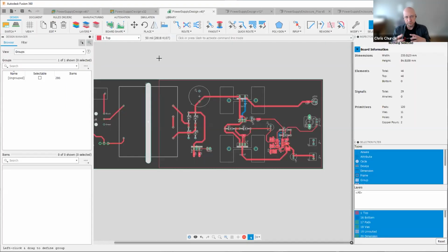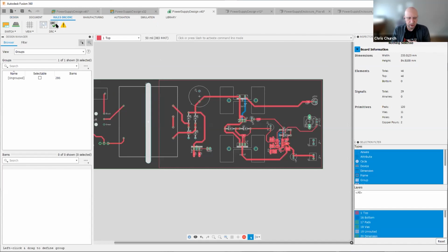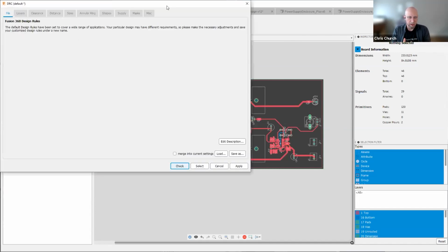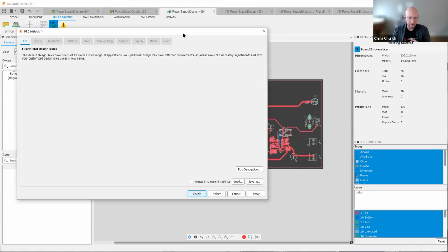So thinking from the perspective of design rules, every manufacturer out there, when we're talking about the PCB and even into the mechanical assembly part of it, is going to have some number of design rules for you. Typically, those will be posted on their website. But with MacroFab, we actually give you the design rule files for Fusion 360 ready to go. I'll actually post a link right here in the chat in GitHub. And then you can just load these design rules for your design, and it will tell you where you're within certain price points or making an unmanufacturable design. It can give you that feedback instantaneously.